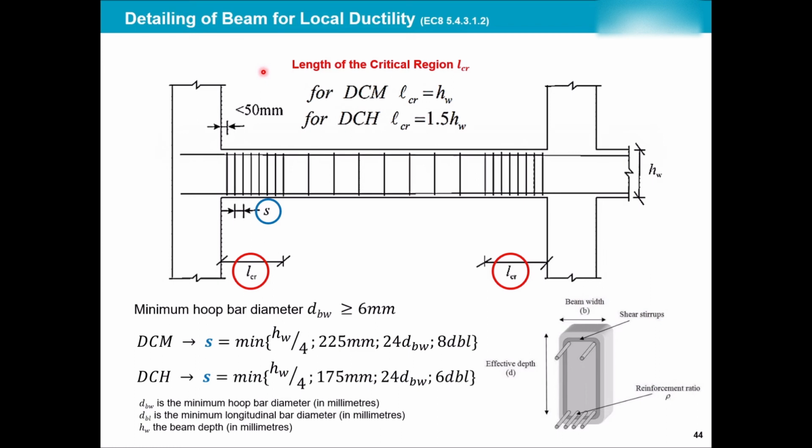One is for your beams and the other one is for columns. All of these detailings are making sure that the capacity design is followed. So it makes sure that your beam is weaker than your columns are strong, and your beam has enough ductility to resist. Remember this: when you design a new beam according to Eurocode, you will have a different capacity in that beam. So you have to analyze the columns with new moments and shear.